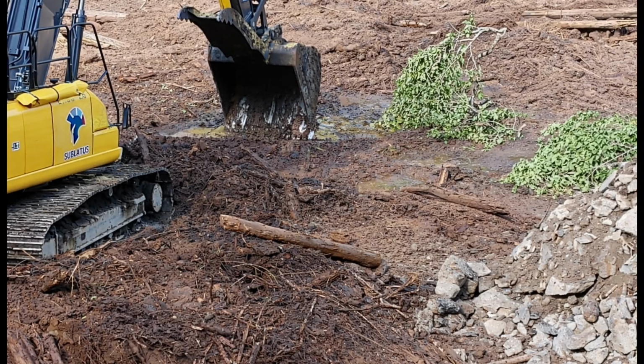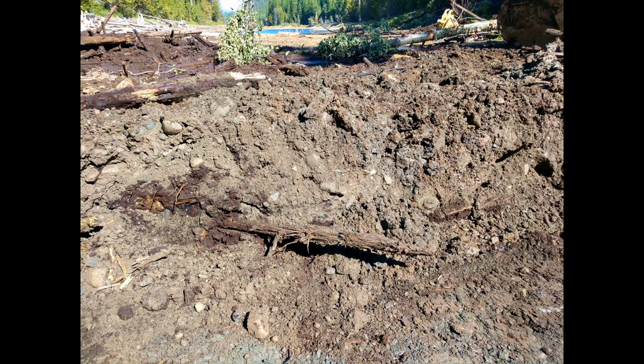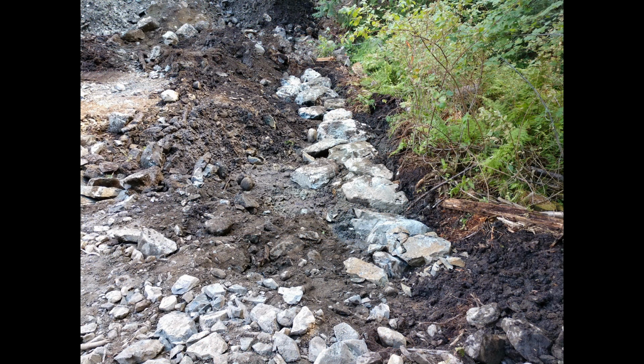The operator excavates the floodplain for the stream after the dam has been removed. Here's where we plan to dig a trench to build a buried vertical grade control structure. It's located where the restored stream would enter the beaver pond. While digging the trench, we uncovered topsoil, roots, and branches under the dam. This showed that the dam had been built on a permeable foundation and without a clay or concrete core that would have controlled seepage.